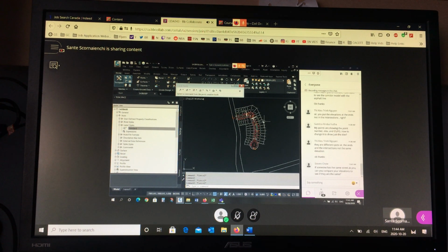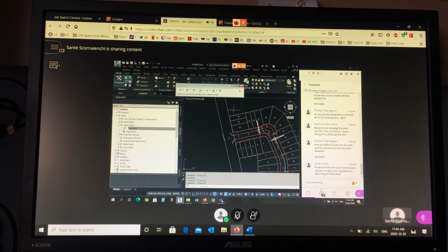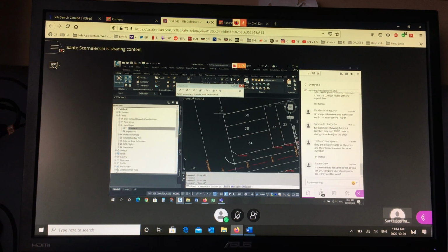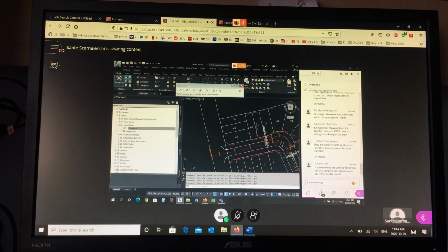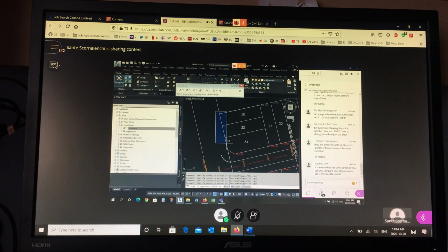Okay. The only exception to this technique, elevations from surface, are these 4 points here, or 6 points. How do you get the front lot corner here? What we're going to do is assume that because this is a proposed subdivision, we're going to propose an elevation here that's comparable to if this rural road was urbanized.